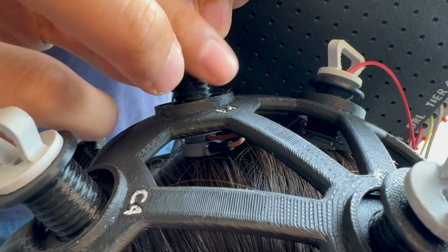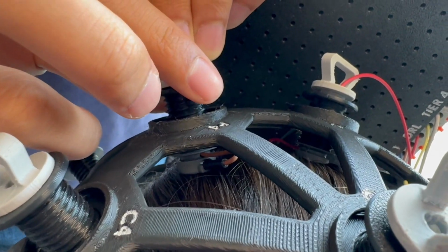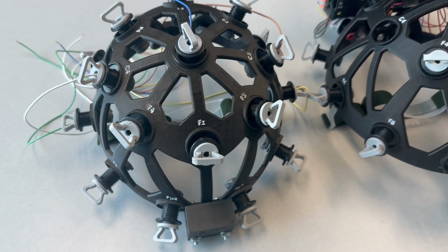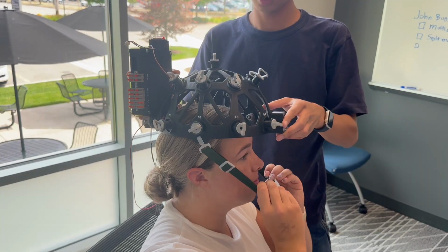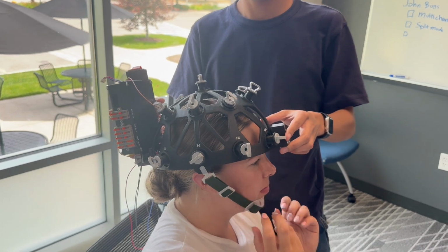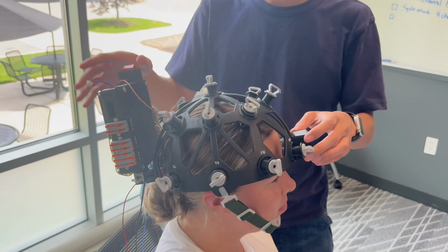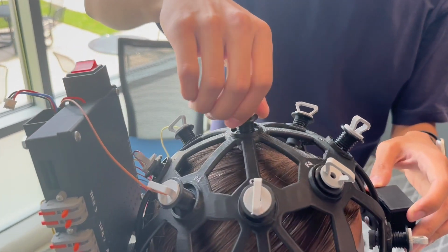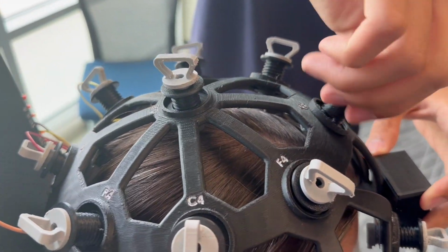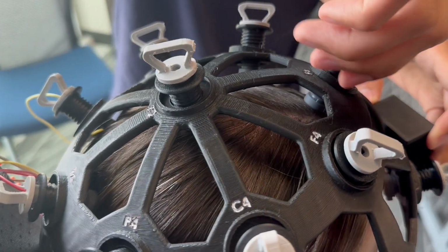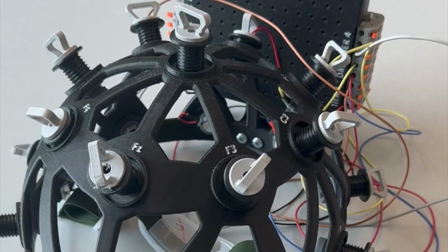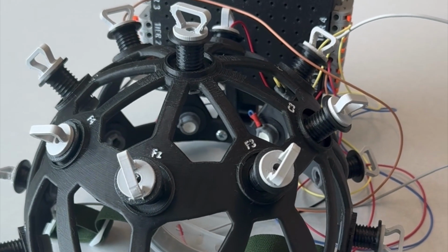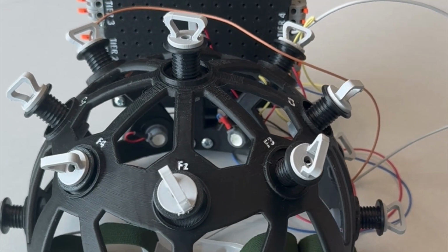The headset is available in 2 size options, small, medium, and medium-large, to accommodate a wide range of head shapes and sizes. Once the electrodes are installed and fully loosened, the user places the helmet on their head. A chin strap and a front-mounted counterweight help stabilize and center the enclosure. All electrode positions follow the standard 10-20 system for EEG signal acquisition and are clearly labeled according to their respective locations.